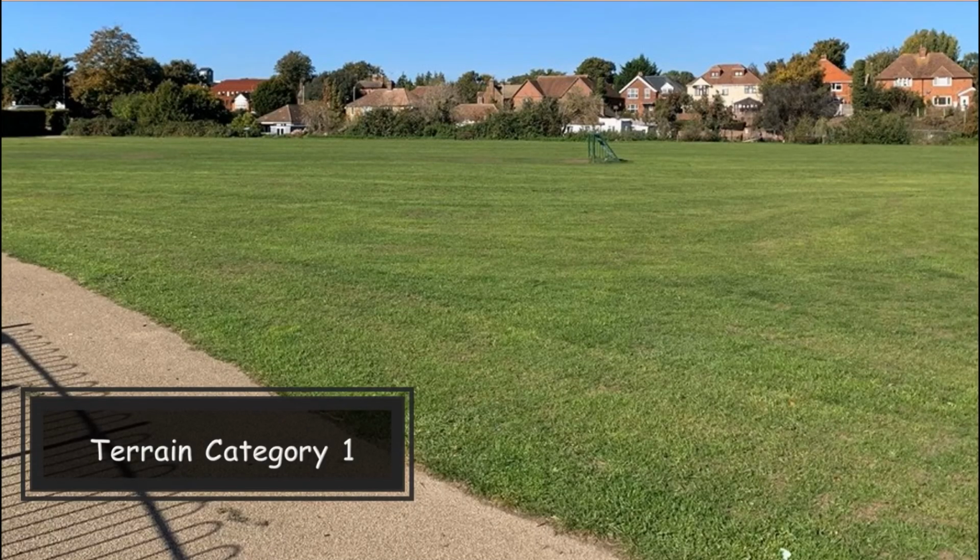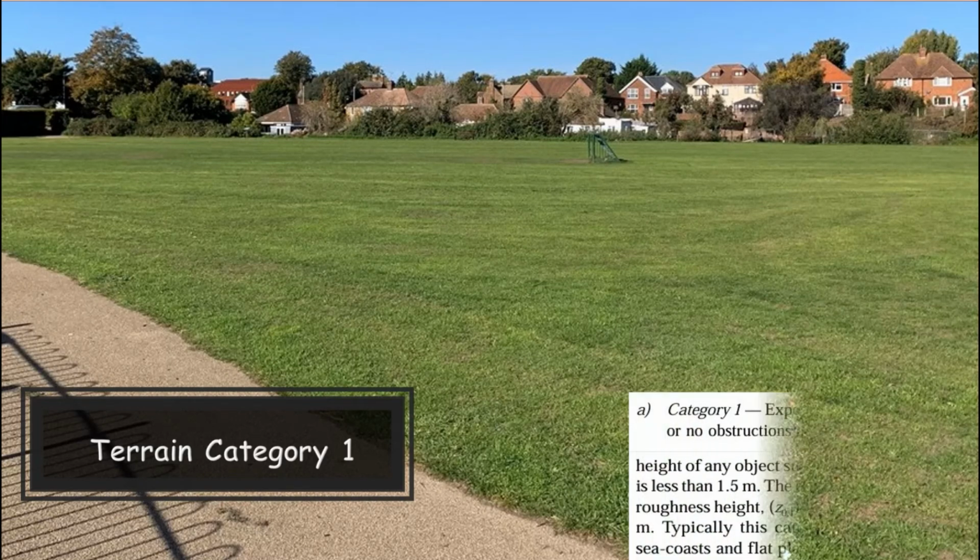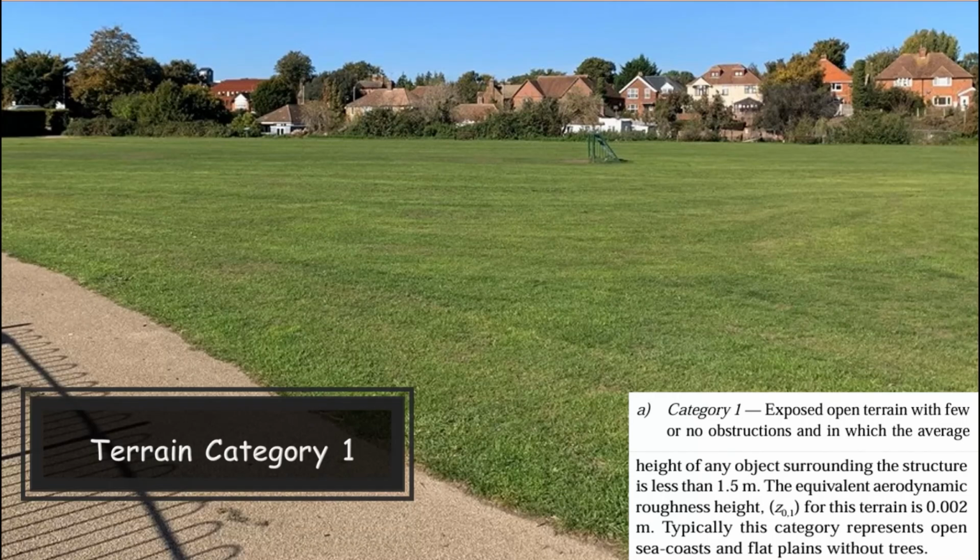The second factor is K2 factor, that is terrain factor. In IS 875, there are 4 terrain categories. Category 1 is the open terrain with few or no obstruction, in which the average height of any object surrounding the structure is less than 1.5 meter. This category mainly represents the open sea coast and flat plains without trees.